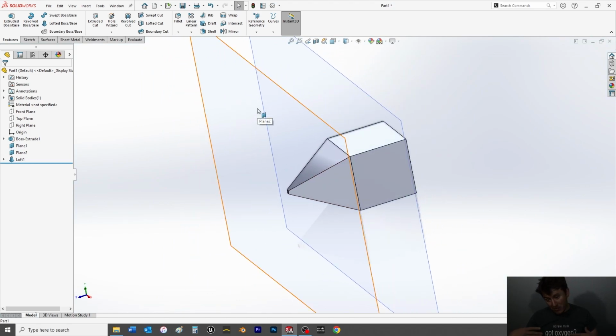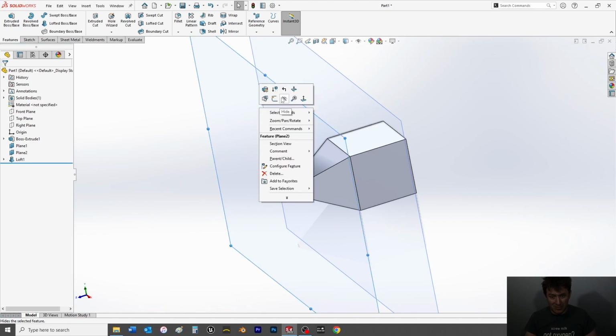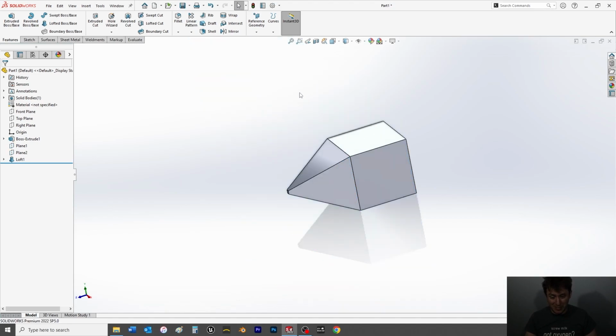So you could arguably, on every single face of this cube, repeat that exact same process and take some serious time to do so, but we're going to speed things up. And again, now this is why I told you to make your cube extruded on the midplane. So we're going to choose the front plane, or whichever plane you made the original sketch on. You could arguably make it on any of the opposite planes too. But to minimize confusion, again, if you chose the front plane, stick with that.